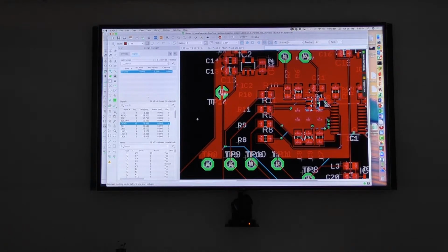If you ask a board manufacturer, they like to have a consistent copper area on the board. If you're talking to high frequency people, they say copper areas that are not connected to a signal can work as an antenna or something like this, and you can have problems, maybe or not, depending on what you're doing.